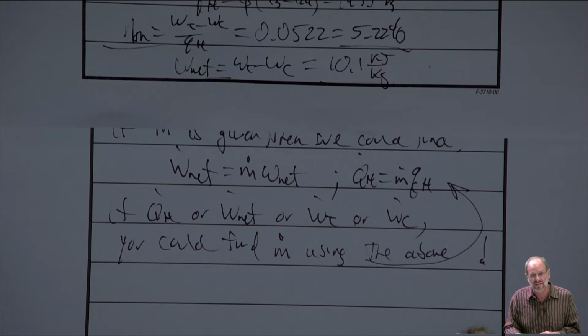We also looked at ideal gases at this point, right? We looked at the ideal gas equation of state. It must have had at least 3 or 4 different versions, right? PV equals RT, PV equals mRT, PV equals nRT. Sometimes V is total volume, sometimes V is specific volume, sometimes V is the molar specific volume. Just make sure you follow the units through if you're confused at all about which form of that equation is correct or proper, and the units will always tell you whether you're doing it right. Nonetheless, we looked at ideal gases at that point.